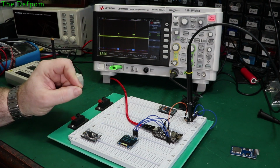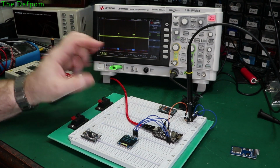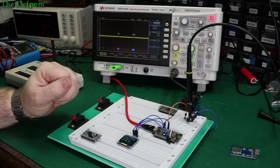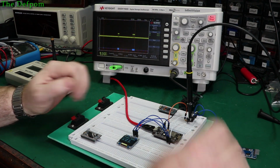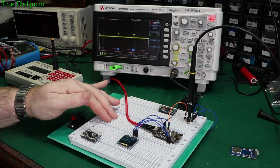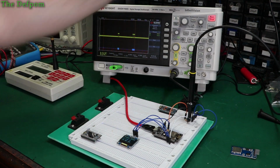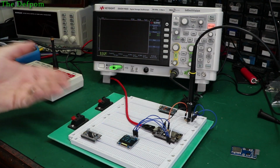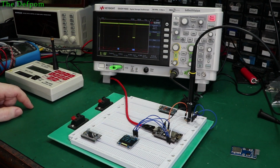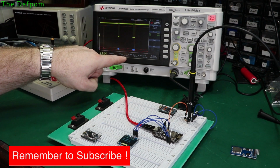So it might be overdriving it very slightly, but it's only little pulses, so it should be fine, I think. At least we know we've got a nice solid on state. It's not going to be in its linear region, it's going to be latched basically. So that's fine. Then we come over to the next pin over, and that's the output from the transistor, which is that serial going to the ESP8266. So doing a capture on that, this level should be about 3.3 volts. There you go, start stop pulse. We get 3.7 volts peak to peak, which is interesting.